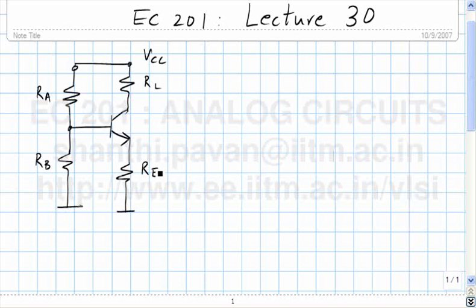Put a resistor in the emitter. And how we come to this solution is, we have seen this in the case of the MOSFET, where we try to put a current source and then try to do without a real current source. We try to use a resistor instead, and we need to use a large resistor. And the question now is, what is the definition of large? And what did we see in the MOS case? What is a large resistor?